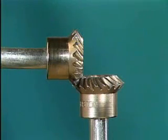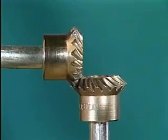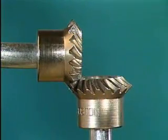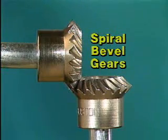Since the teeth engage gradually, the noise produced by the gear set is reduced. And since the gear teeth are twisted, more gear teeth can be meshed at the same time. This increases the load that the gear set can transmit. Bevel gears made this way are called spiral bevel gears.